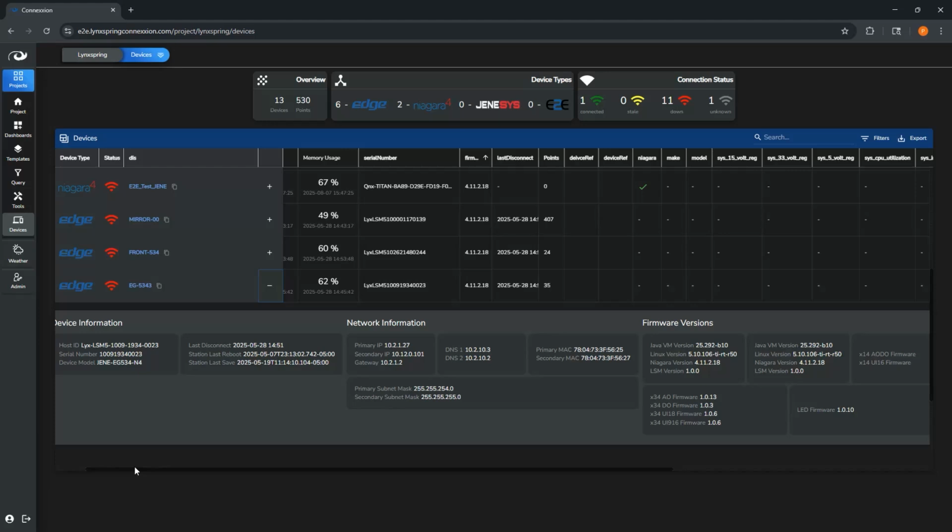You need to know why. One of the first things you're probably going to do is take a look at some of the hardware metrics. And you notice that my internal temperature is 180 degrees. It's been 180 degrees for 3 days. Somebody installed this device wrong is kind of the information that you're figuring out there, right? It's not ventilated. They're pumping too much electricity through it. Something's wrong in the internal temperature of the device. You basically burnt the thing up.